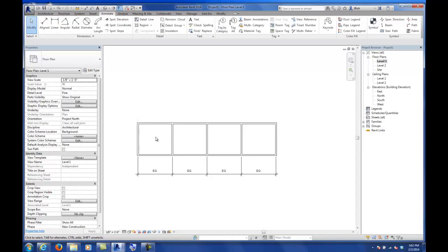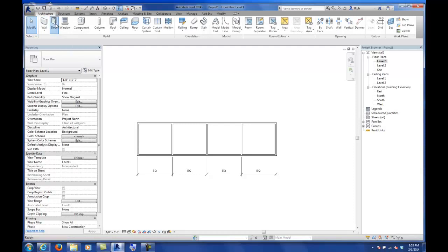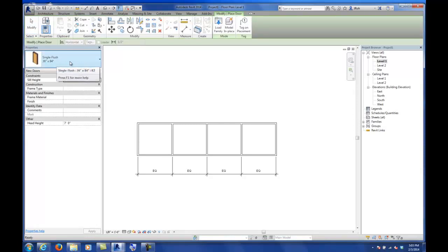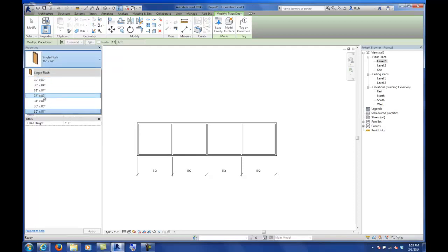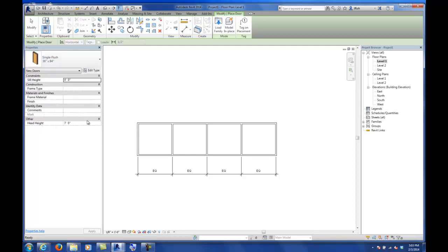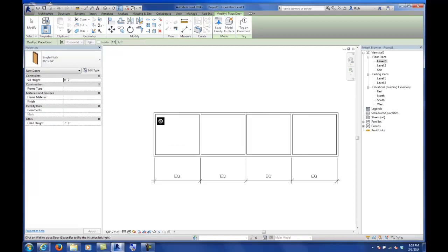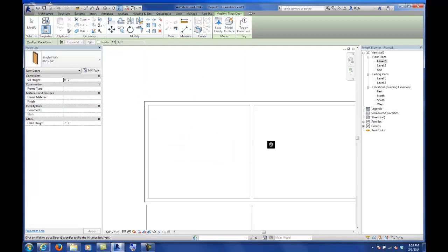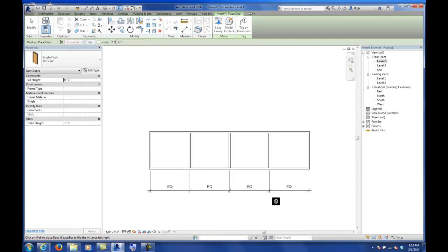Another component to that is you can also lock components to there. So let's say we have doors. We need some way of getting into these offices. And again, right now we're just drawing in 2D. We haven't really looked at this in 3D yet, but we are making a model as we're drawing here. If we go to Architecture and click on Door, I'm just going to use whatever the first door is that pops up because I don't want to get into that too much right now. But again, you'll see there's different dimensions for this one door type. And we can go ahead and place this door, and you'll notice we can't place it until we hover over a wall. You'll get this little no symbol anywhere else.